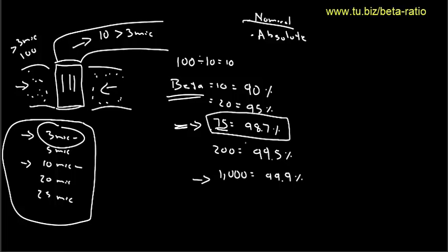Because that's when the game of words starts. You have a beta 1000, you have a beta 10,000, and so on, right? It's a much higher number, but it's very important to check what beta and micron you may be looking at, and it has to be guaranteed. It has to be absolute filtration. On nominal filtration, you can also put whatever range you have for micron rating, but you don't have to give an efficiency for the filter. So that is how you calculate the beta.